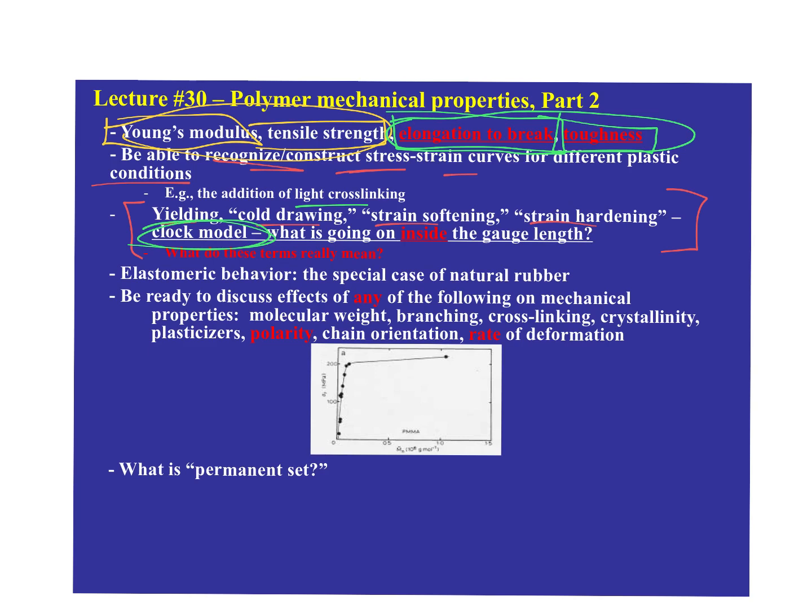We're talking about what happens inside the gauge length of these materials as that microstructure or that architecture is destroyed by the process of being sheared during the deformation of these dog bones. And so we have this advanced view of the inside of the gauge length of a dog bone now, in which there's a shearing process, the destruction of microstructure, and then that propagates down the length of the dog bone. We start at the neck and move down. All right, so you should have a much better understanding of what goes on in these systems and how the crystallinity, spheroids, everything that's in the system is going to be influenced by this process.